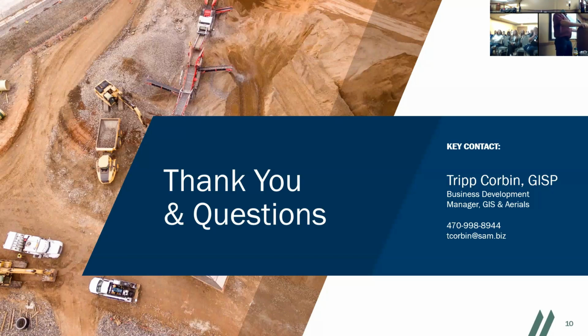Yeah, so what I do is when I first bring it in, and it's not projected right, the first thing I do is select all those lines and update COGO attributes, and I've got them. Yep. Then when I reproject them, regardless of how they've been rubber sheeted, when I go ahead and attribute, I'm pulling the true COGO attributes in. Yeah. So that's all. Yep.